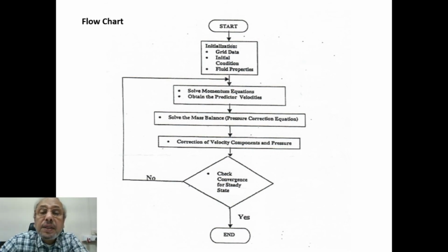Then initial conditions are set and fluid properties are obviously needed. We solve the momentum equation to obtain provisionally calculated velocities. Predictor velocities means provisionally calculated velocities.